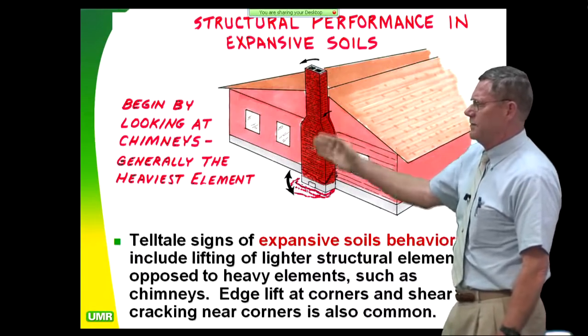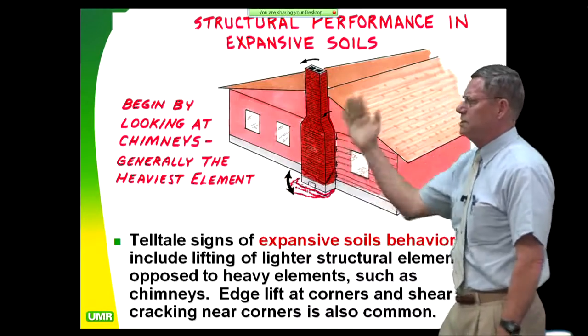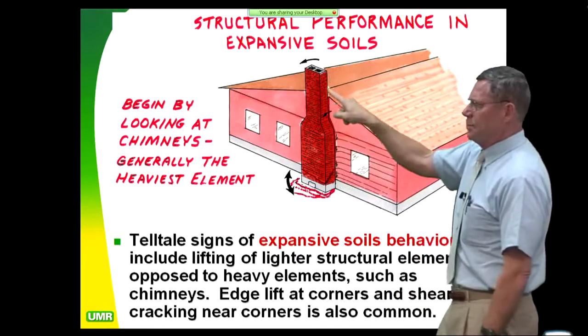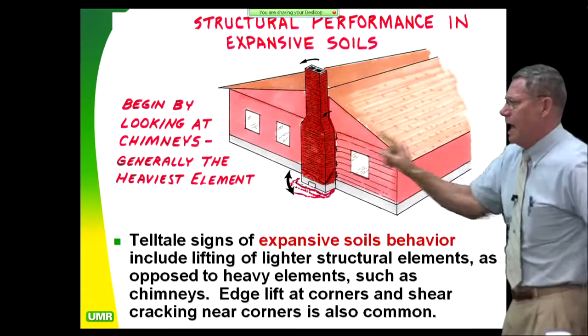And sometimes if you have a little bit of bearing problem out here because they have poor drainage, the chimney will start tilting away and separating away from the house, and you're going to get dry rot down the back of that. Now, word of caution.